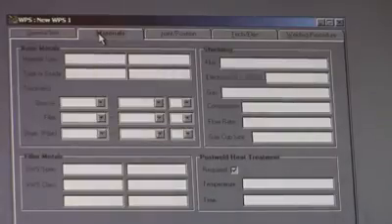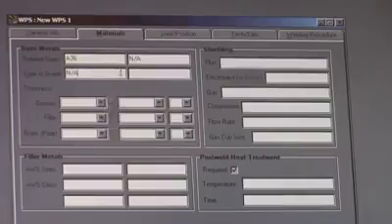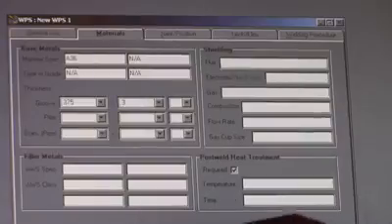Your base metal specs, we're just going to assume they're going to be using an A36 steel. It's very common. We don't really have a type of grade. And we're going to go with a vertical up, like I said. Let's just say it's a 3/8 groove thickness, 0.375 to another 0.375. That's going to be in inches.